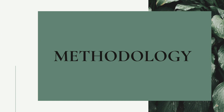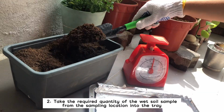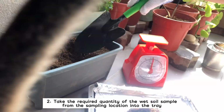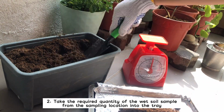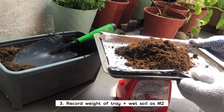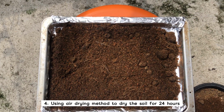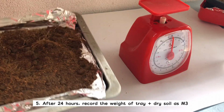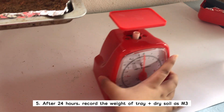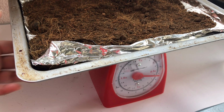For water content determination, the first step is to weigh an empty tray and record it as M1, and then take the required quantity of wet soil sample from the sampling location into the tray, and record the weight of tray plus wet soil as M2. Next, by using the air drying method, dry the soil for 24 hours, and after 24 hours, record the weight of tray plus dry soil as M3, and repeat the test 3 times to find the average.